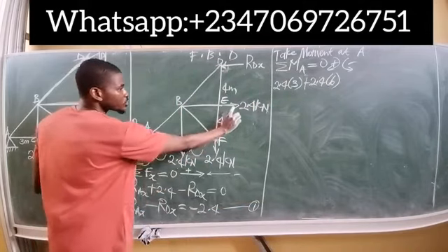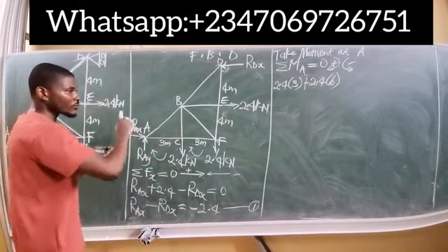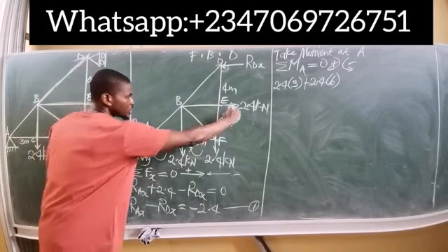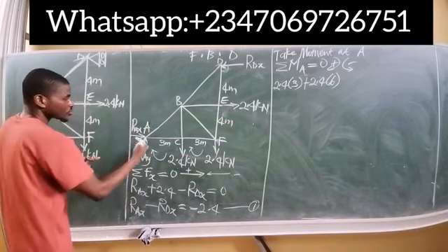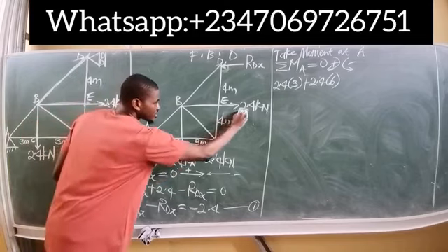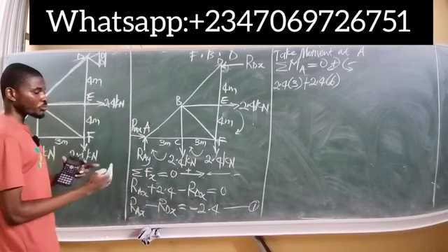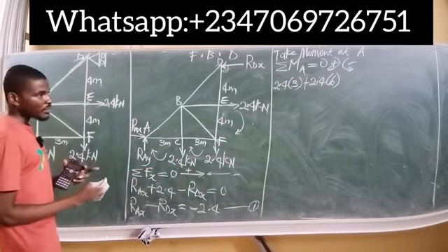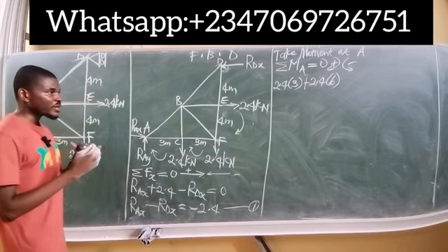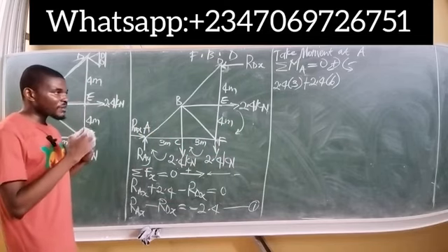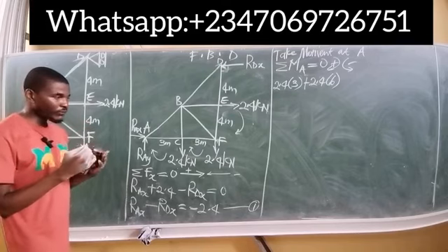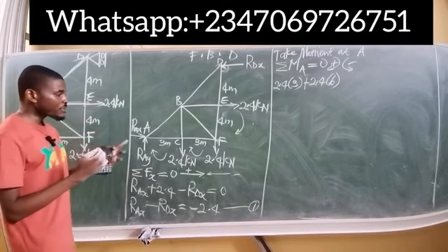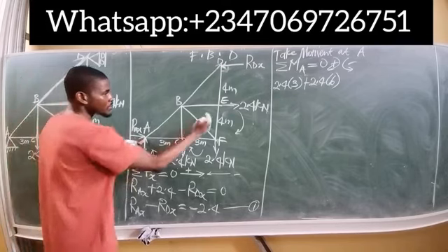Next I have this 2.4 kilonewtons force. This force is pointing to the right, which means it will turn about in this direction to take moment at point A. And this is also positive to our direction. That's clockwise. But then again, moment is simply force times the perpendicular distance which the line of action of the force makes to the point of moment. This is the point of moment, point A. I want to take moment of this force.